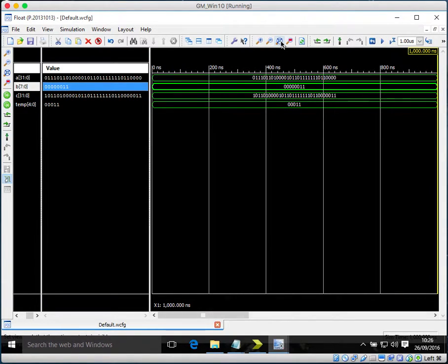So there. So basically the select line tells me that I need my input to be shifted to the left by 3 bits. Now that means this bit should come here and this bit should come here. Let's just check. 110. So yes, this is the 29th bit, the 30th bit and the 31st bit. Same as here.